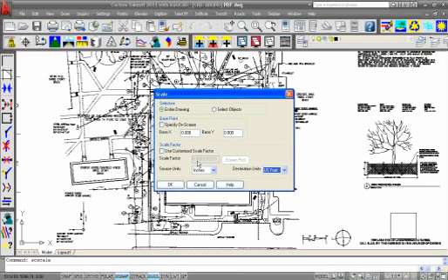You can see the scale factor is grayed out, but it's 0.083333, repeating. So the program automatically knows those conversions and will scale the drawing accordingly. It's not something that you have to type into your calculator each time to figure out how to take a US feet drawing into metric. It will calculate that scale factor for you. On this job, there's no simple conversion for that. We want to use a customized scale factor.